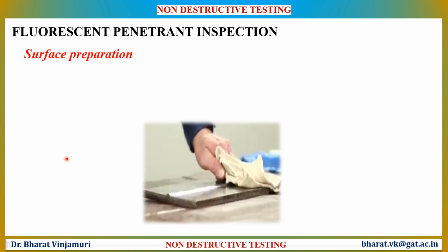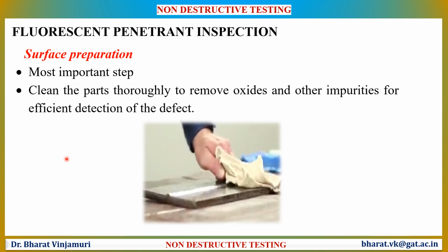Surface preparation is the most important step in the process. The surface must be free of oil, grease, water and other contaminants. The part to be inspected has to be cleaned thoroughly to remove oxides and other impurities for the efficient detection of the defect.